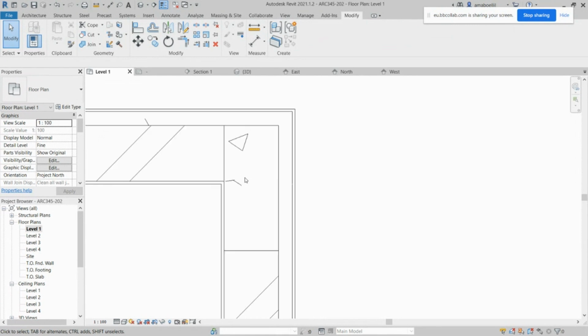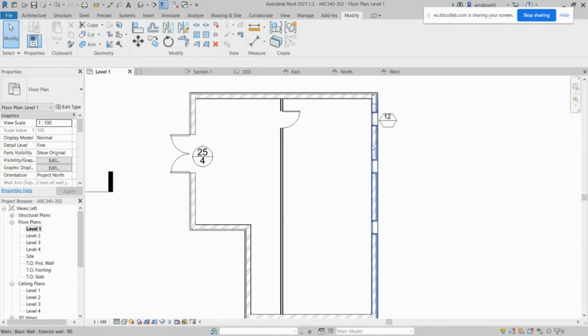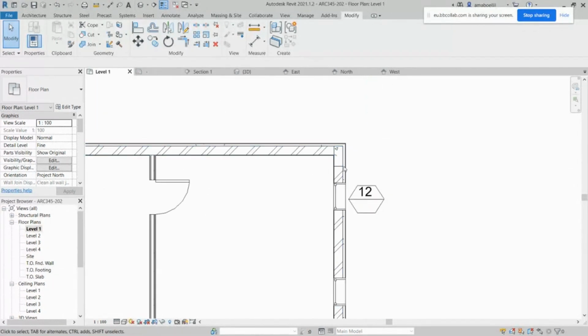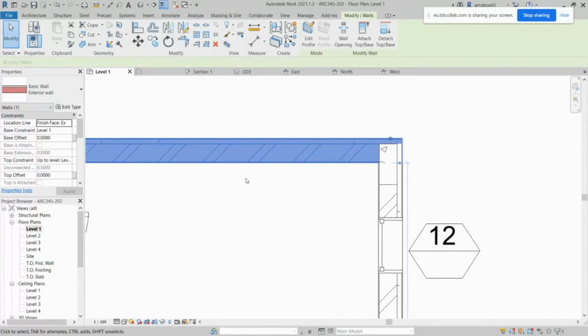Let's move on to one other detail in the structural or architectural drawing. Usually, the walls are not going to be shown patterned, no pattern to show in the wall. On the other hand, the columns, any structural material that you cut, has to be hatched with a specific pattern. So what can we do? You can go to this brick, and we said that the one in the middle is brick common.